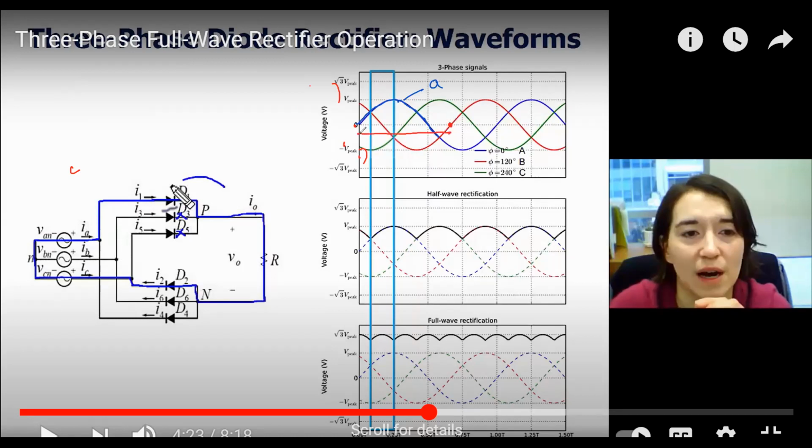This span must be minus 120 degree, right or wrong? Yes. So red one is the B phase, and C, of course, minus 240 or plus 120. So green one is the C phase. Okay, I'm changing the color. This is your B, and this one is the C.